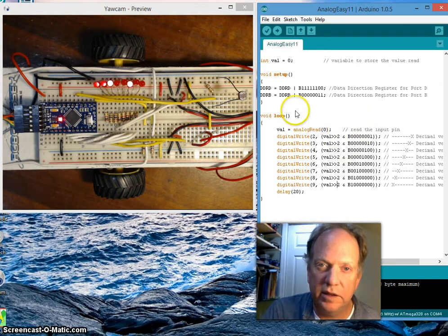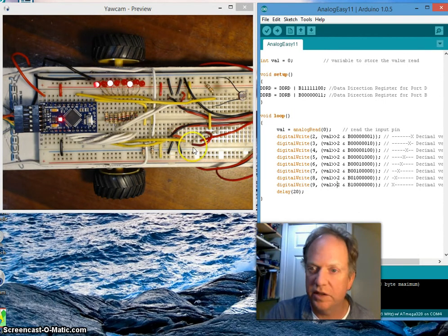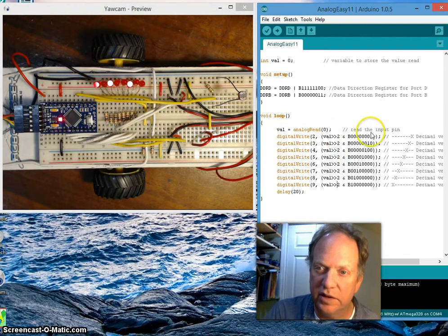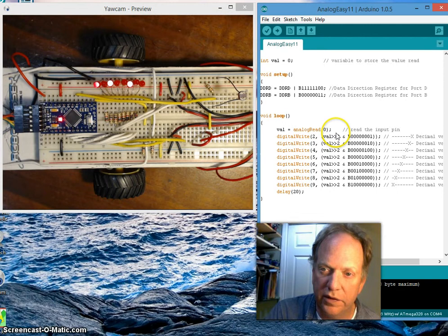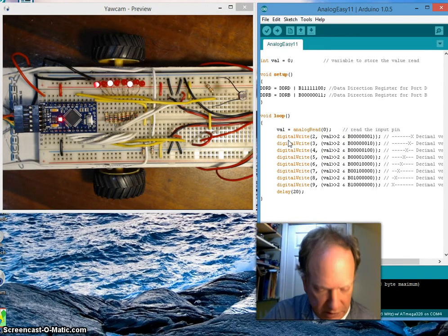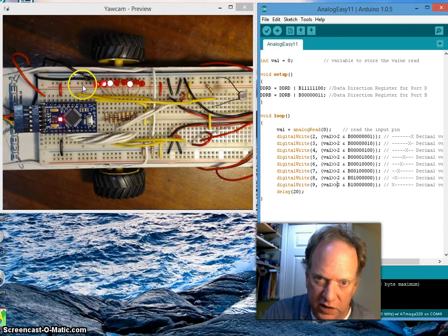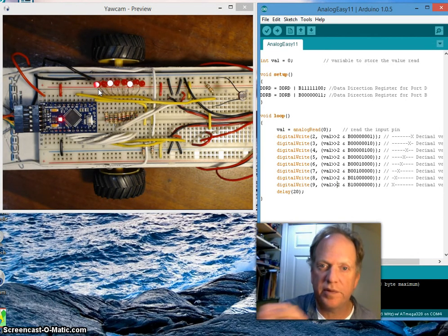Keep in mind, the processor itself is able to do 10 bits of resolution, but I've only got 8 bits of display. What am I going to do? Well, the easiest thing to do is simply to shift. These 2 greater-than symbols mean to shift. I'm going to just get rid of the lowest 2 bits. You can see how these are flickering already right here. You can imagine the 2 that were even smaller than that are flickering just as fast, if not faster. They're undecided, they're ambiguous. So let's just drop them from the thing altogether.